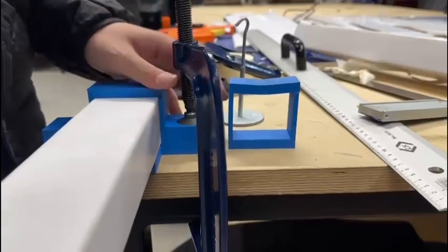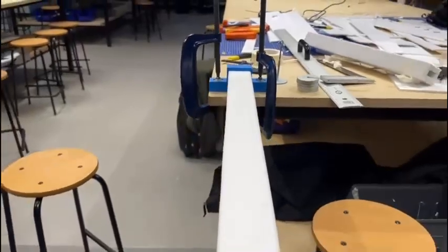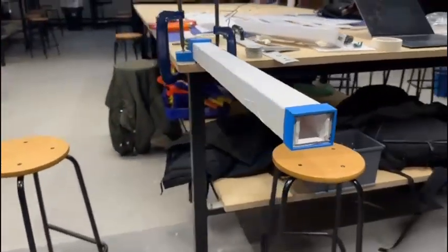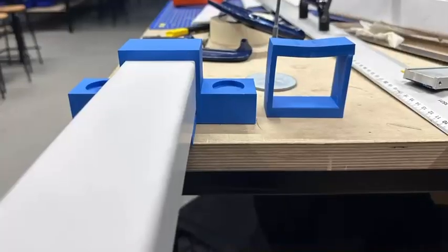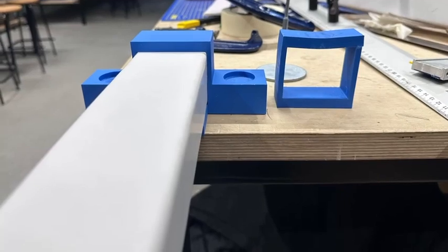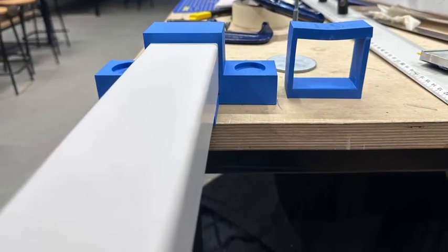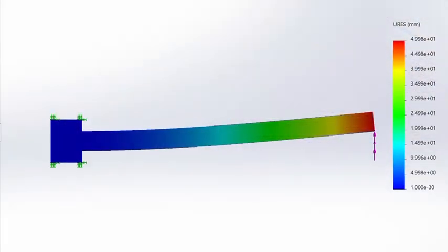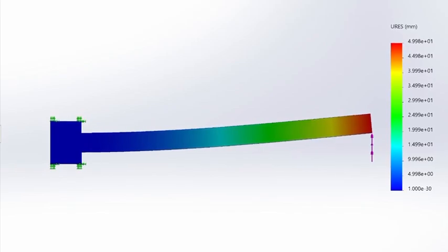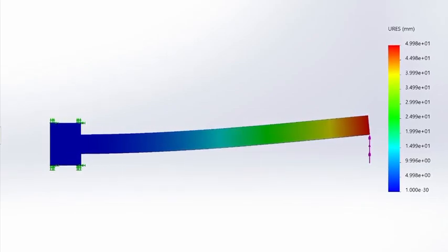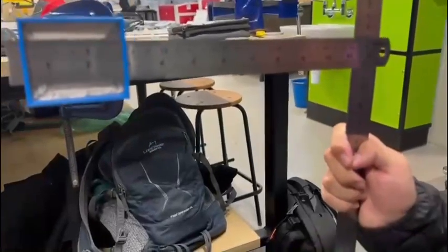After our spar passed the requirements in the Excel document, we needed to test using practical experiments. To carry out these experiments, we needed to create a sturdy base for the spar. We 3D printed a sleeve for the spar to hold it securely during the bending and torsion tests. To test if our spar met the torsion requirement when a max load was added, we made another component to hold a ruler to which masses could easily be applied.